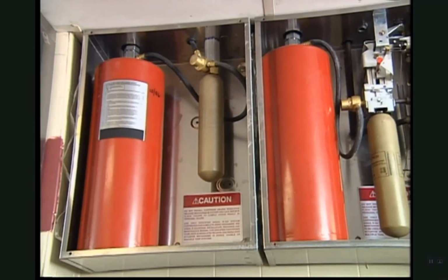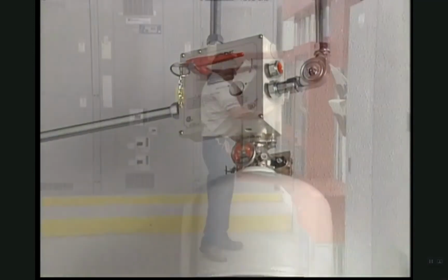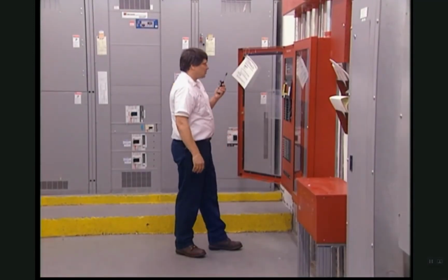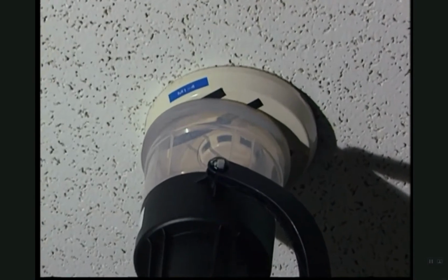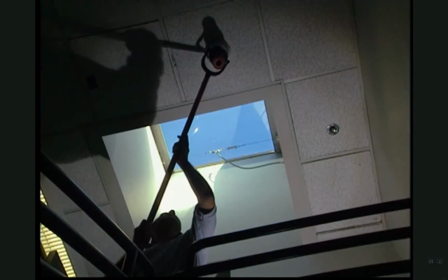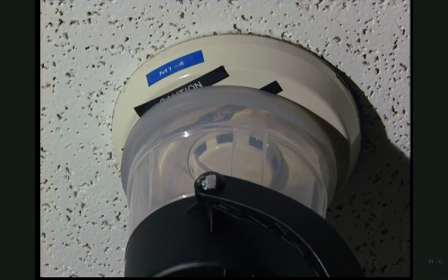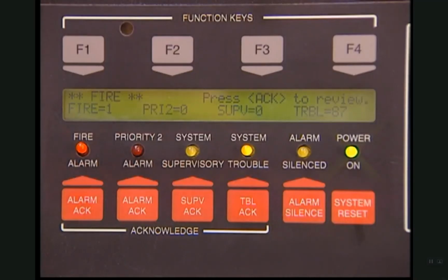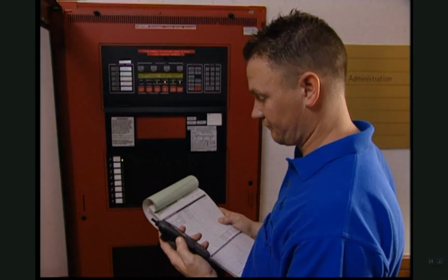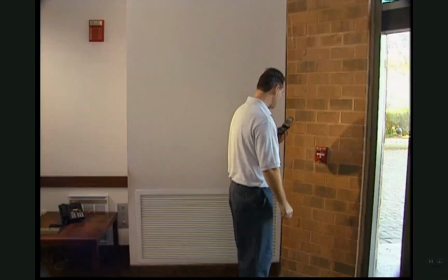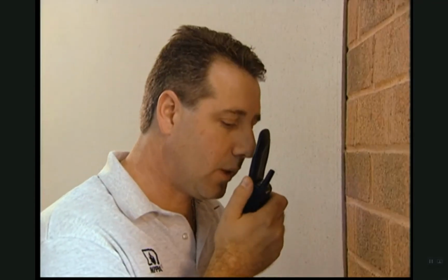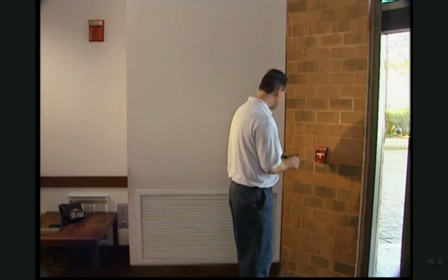Typically, the switch is mechanically or electrically operated, and receipt of alarm signal at the control panel is verified. The method for testing a heat detector depends on whether or not the detector is restorable. Test restorable detectors with a heat source according to manufacturer's recommendations. You are looking for a response within 1 minute. Non-restorable detectors should not be tested by heat. Manually test fire alarm boxes following manufacturer's recommendations.